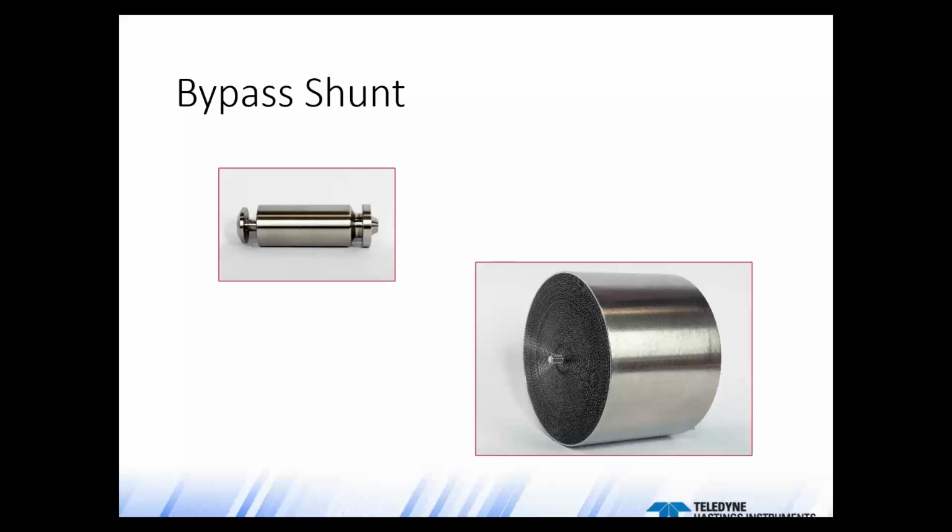A well-designed shunt forces the gas into laminar flow such that the flow is well behaved. The flow is often conditioned at the inlet to avoid turbulence. Now you see the shunt at the bottom right there has small corrugated passages to ensure the laminar flow. So there are many different shunt sizes, but no matter what size, the role of the shunt is the same. It will give a pressure drop across such that the sensor has about 10 standard cubic centimeters per minute or so near full scale as flow passes through the body. Of course, larger shunts require larger flow meter bodies and fittings and line sizes.